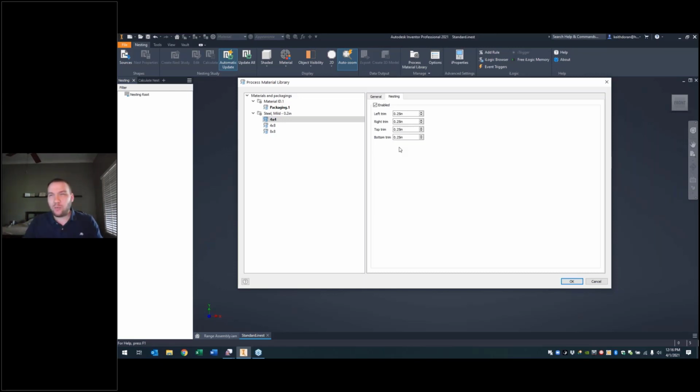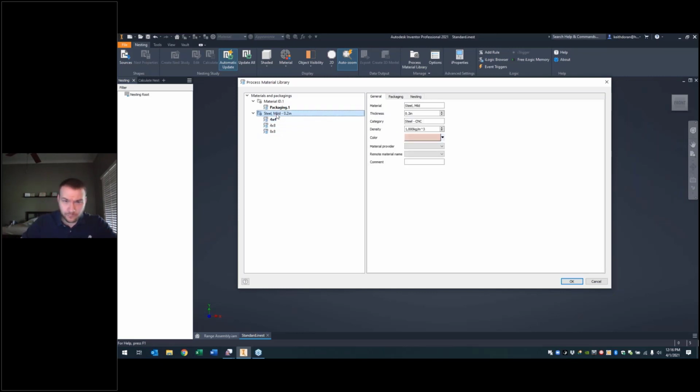I can specify what range around that material I want to use for holding that material steady during that process, and essentially just define that trim boundary around the sides of the part. And the nesting will take that into consideration. So again, each one of these can be defined, and within that shape, we can lay all that out. And again, we can also define each nesting's boundaries per material within the space.